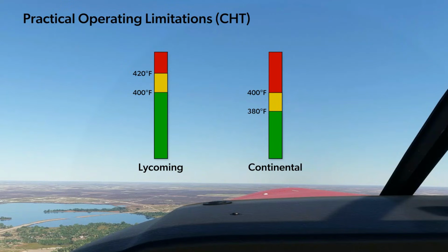Now, some aircraft run hotter than others. And it's not like if you get to 421 degrees on a Lycoming, you're going to do damage. But the more that you can keep this below these levels, the better. I fly pretty often a 180 horsepower 172 based in Wisconsin, and it just runs hot. And so I'll often see after takeoff CHTs on the hottest cylinders around 430, even on a not especially hot Wisconsin day. And so in that case, CHT is a limiting factor.